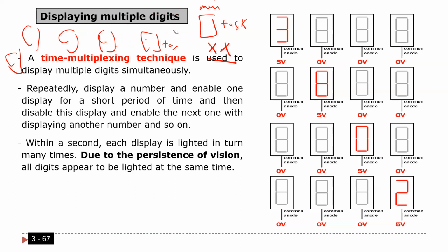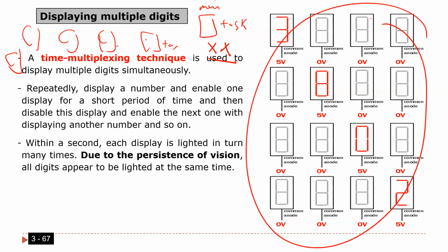So what is the relation between what I explained right now and time multiplexing? Simply because time multiplexing is a task. You can put it in the main, or you can put it in the SysTick, as I'm going to explain right now. Last time I explained how you can do the time multiplexing in the main. Today I'm going to explain, and it's almost the same thing, how I can do it in SysTick.